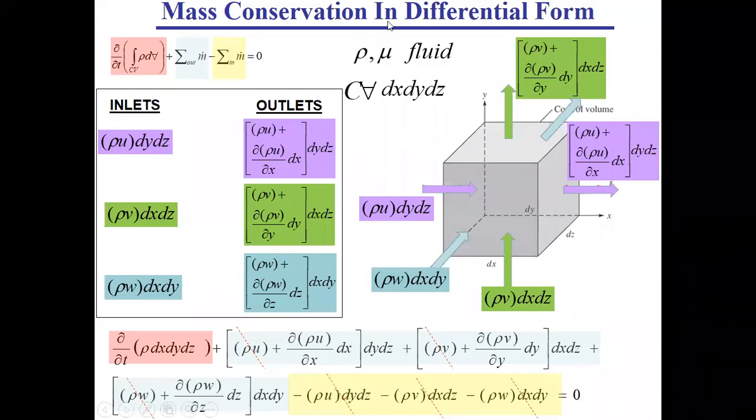Okay, so we were saying that if we want to study the force balance on this element, sum of forces equals MA, we need to consider the dominant forces acting on it. So let's say for the body force, we take the weight. The weight for this element is m, the mass, which is dm because it's a small mass, times g.